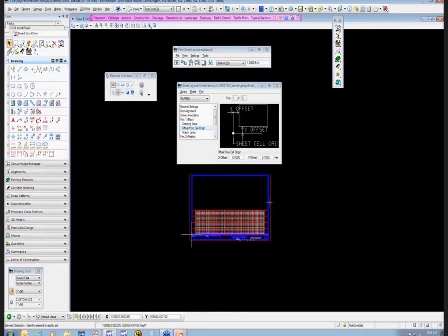Okay, so I've got 14 feet from blue line to blue line, and there's 5.4 feet from this red line up to the blue line. That's my drawing area, so when I look at my offset for my cell origin, if I'm going to use all of that space, which is the 14, then it's going to say, okay, go up, plan profile. My cell origin offset X is set to 0, and then my Y offset is set to 0.1. Why is that?